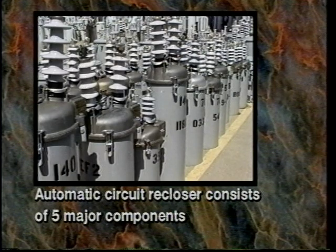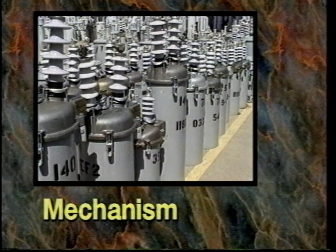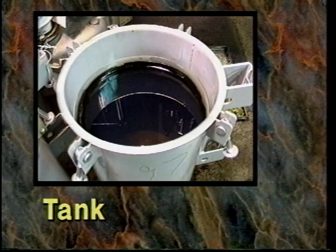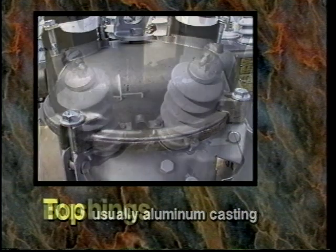Construction. An automatic circuit recloser consists of 5 major components: tank, bushings, mechanism, interrupter, and controls. Tank. The tank is the part of the recloser that houses the interrupter and tripping and closing mechanisms. The tank is usually made of steel, and the top is usually an aluminum casting that supports the various components.